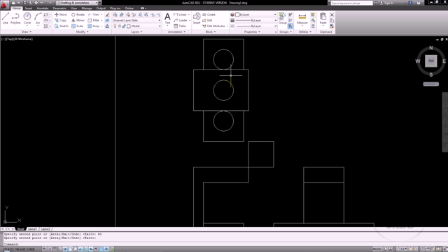Now you can see that this hole right here theoretically would be covered by this top piece. However, I know that I have a hole that goes through the top with a diameter of 30, and those center points mathematically are going to line up. So I'm going to come in here with the diameter 30 hole, so you can actually see this hole through this hole.